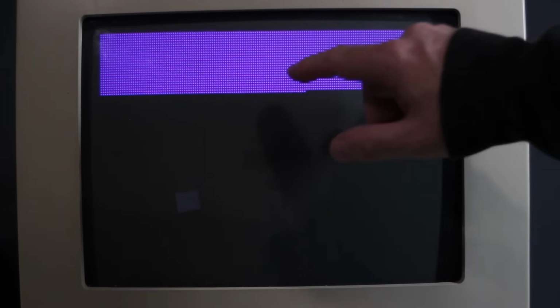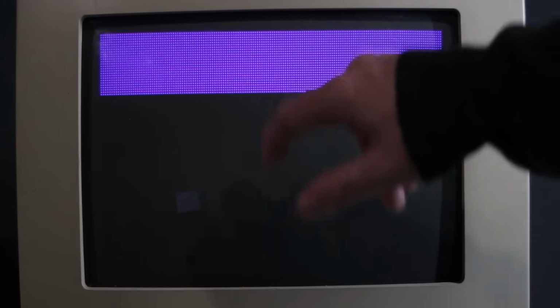Now, I don't know what's going on here. I'm not sure why we've got just a quarter of a frame here. The interesting thing is that I'm doing memory DRAM refresh about 4 times per frame, so if that hangs the first time it runs, then that might explain what's going on here. Interestingly though, I've not got a parity error, so I would kind of expect that if the DRAM refresh wasn't working. So I'm a bit puzzled about that.